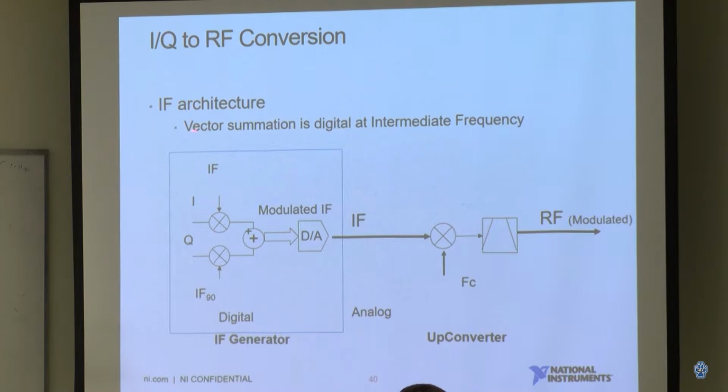And further, we can break it into steps. We can consider the modulation conversion just like an intermediate frequency step. We can add another mixer to up convert the frequency even higher. The reason for doing this is that if you're using a single step conversion, you don't have a lot of capability to do filtering.